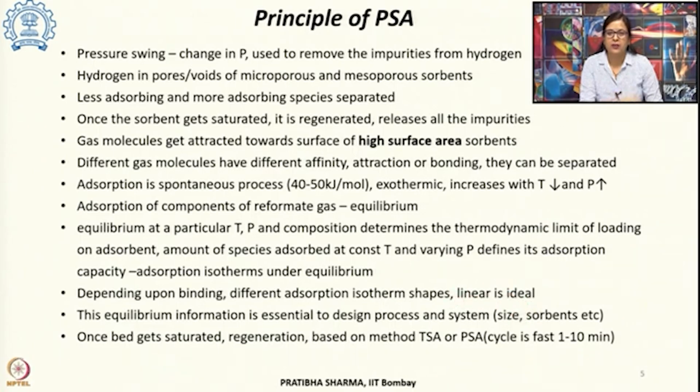If it is non-linear, some regions of the isotherm may have a lower pressure. Now, in order to desorb such a system, we will require even lower than that particular pressure, and in that case the pressure requirement may be as low as a requirement of vacuum. That may add on to the cost, to the energy efficiency of the process. So, ideally it should be a linear isotherm.